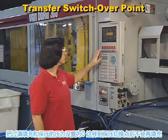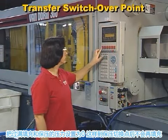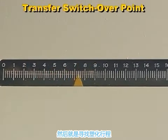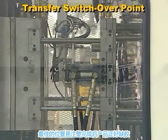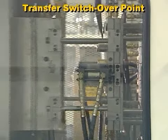Set the packing and holding pressures to 0 so that they do not cause plastic flow after the transfer point is reached. The next step is to find the best stopping position for the screw during screw recovery. The proper setting will be the position that results in a shot volume that, when injected into the mold, produces parts that are just slightly short.